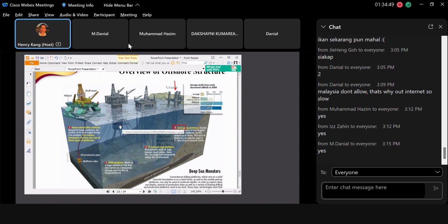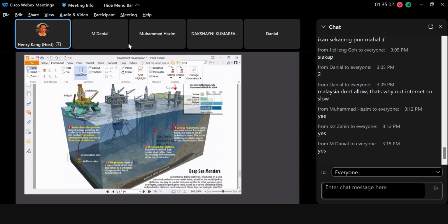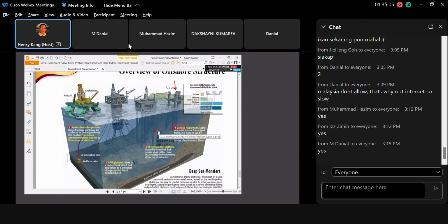But you can imagine for the TLP, if I lose all of the tendons, what will happen? The hull will capsize. Capsize means upside down. However, for the SPAR, if I lose all of the tendons or all of the mooring lines, the column still manages to maintain upright.